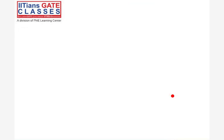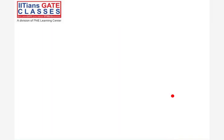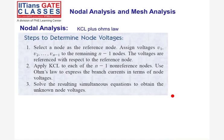So first thing is nodal analysis. What is nodal analysis? As I've written here, KCL plus Ohm's law. Nodal analysis is nothing but your KCL plus Ohm's law. So how do you do this nodal analysis? Select a node as a reference node, assign voltages V1, V2 and so on up to Vn minus 1 to the remaining n minus 1 nodes. The reference node is usually taken as the ground node. Ground node is the reference node.